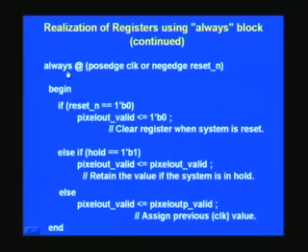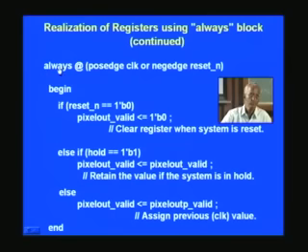So once again we use always at positive edge of clock or negative edge of reset, and you will notice that when you go through the course, you will get again and again the very same structure all through, and that is the beauty of this structure. Especially when you want to redesign something or even start on a new design, all you need to do is just save your earlier project's file and simply rename it to suit the new design. So that way it helps.